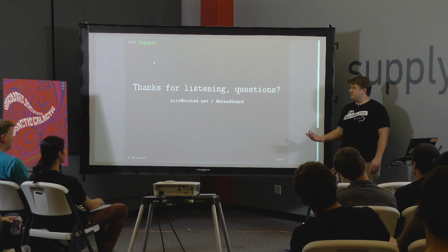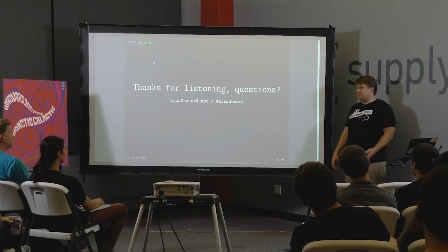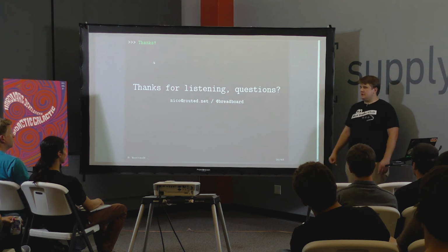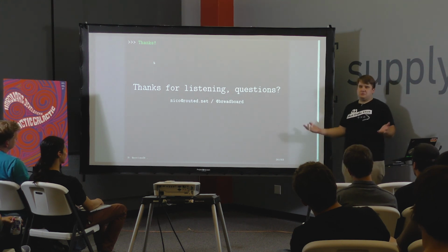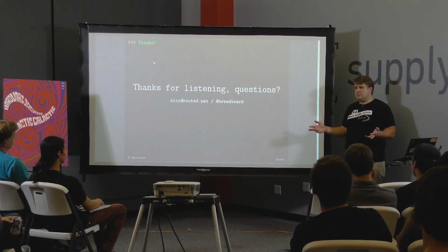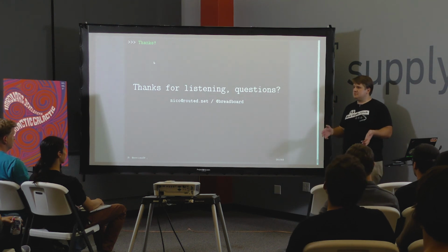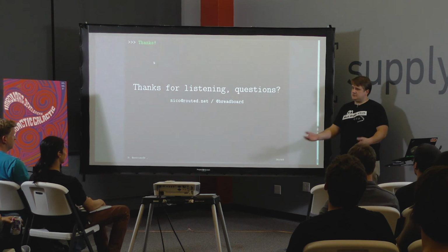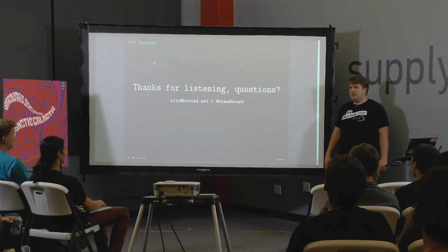But then also, we make our system fault tolerant, especially for soft faults. Because firmware is hard. Firmware will crash. If you can recover from a firmware crash quickly and get back on your way, then to me, that's much better than having a system that will always stay up. So we'll design for that. We'll try to have something that's nimble, I guess.